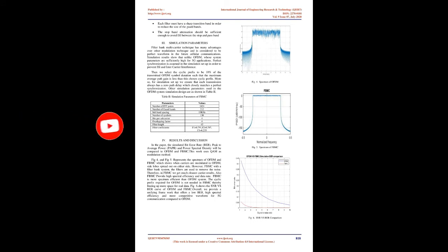The key features of OFDM are the IFFT/FFT pair. These mathematical tools are used to transform several signals on different carriers from the frequency domain to the time domain in the IFFT and from the time domain to the frequency domain in the FFT. The receiver part performs the down conversion of the signal and converts the signal into the digital domain by using ADC. The synchronization is also needed during reception. The OFDM symbol is demodulated by using an FFT.